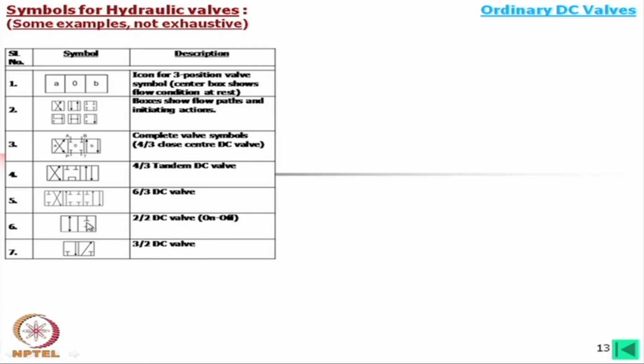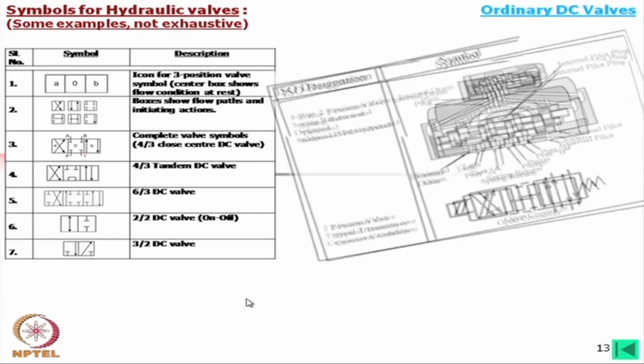Now, this is also a 2 position valve, but as you see, these 3 ports are there. That means, if we consider the main port, this pressure port, when this pressure port is stopped, the oil from the actuator goes back to the tank, and when you are connecting to this actuator, then your drain connection is off. Okay. So, you may need such a valve for some operations.